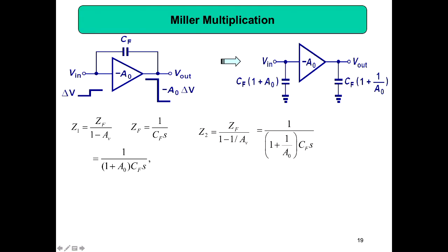If you are traveling with the signal, you might think that the signal encounters maybe this capacitor, and maybe both are coming in parallel. Not that capacitor. Actually, the signal will see a very big capacitor at the input. So the effect of a capacitor between your input and output is that the signal will see a very big capacitor at the input.